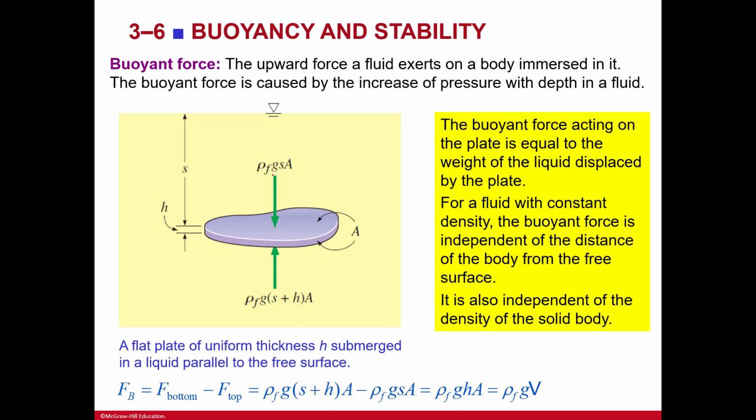Buoyancy force. The upward force a fluid exerts on a body immersed in it. The buoyancy force is caused by the increase of pressure with depth in a fluid. So here is a flat plate of uniform thickness h submerged in a liquid parallel to the free surface. And so you see here that you have not only a pressure down, but a pressure up as well. And then this denotes our atmospheric pressure. And then we have a height of the plate and then a submergence depth.